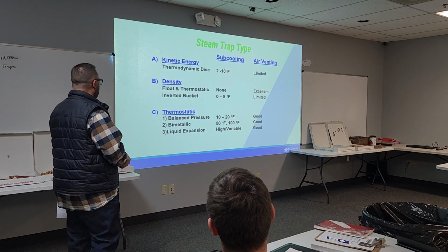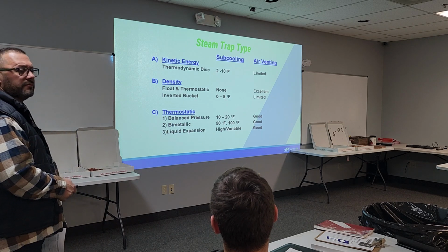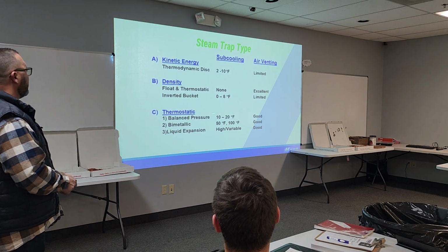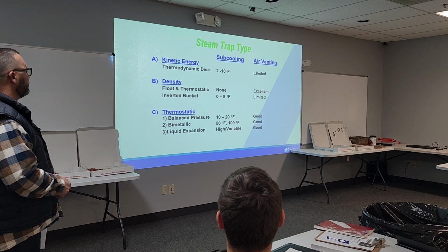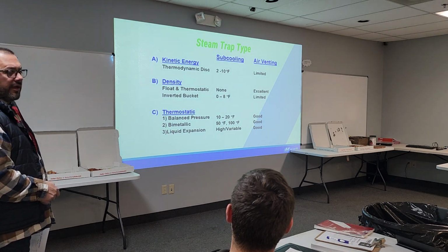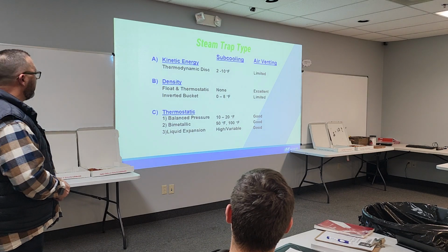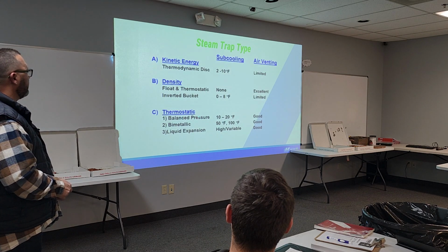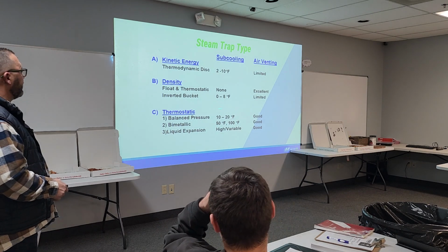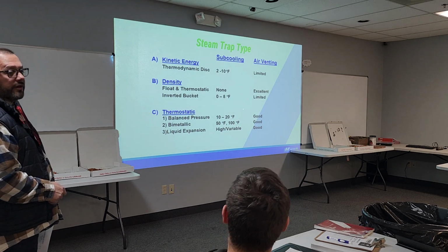Thermostatic traps, these I really see more as like an air vent. We use them a lot, and we started doing some more pharmaceutical jobs down in Columbus. There's kind of a boomtown thing happening, and we've got some pharmaceutical and food plants and different things. But you'll see these a little bit in hospitals on certain applications, but we really don't see a ton of them, and I see these really more as like an air vent.